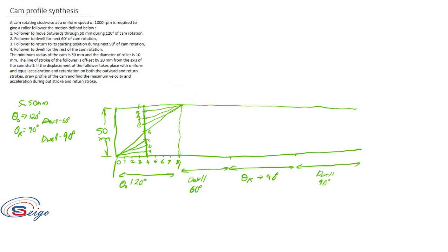Now you can mark 1 with this A. You can mark 1 over here, then 2 with this point, 3 with this line, 4 is this line, then 5 with E, 6 with F, 7 with G, and H with 8. Now by using a smooth curve, you have to join all these points. After that, you will be having the dwell. So the profile will be like this.